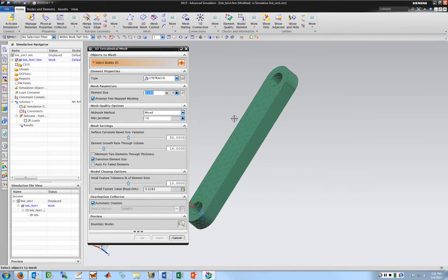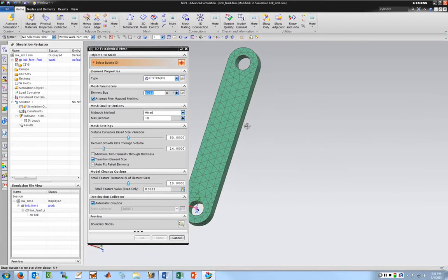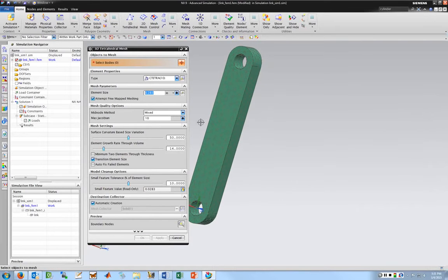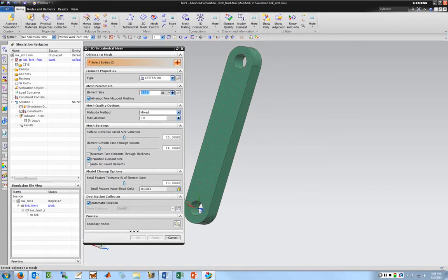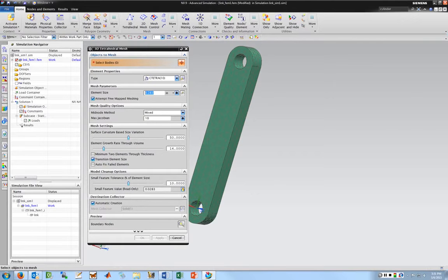This is really simple. So you can see that mesh. I mean, it would probably work. The stress somewhere in the middle would probably be okay, but up here around the bolt circle, I wouldn't trust that kind of mesh. But again, if you're just interested in a ballpark in the middle, you could try this, but you still probably want to try it at a smaller mesh and see how the results change. I'll talk more about that later.